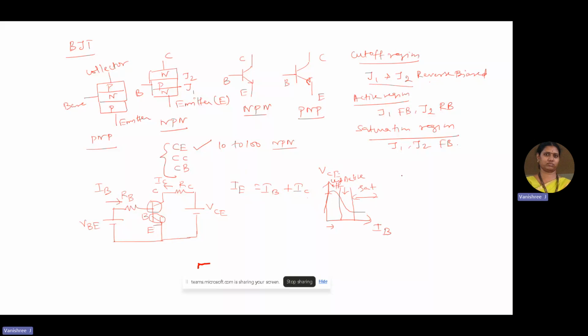So coming to the characteristic graphs, input-output characteristics. Input characteristics is drawn between VBE and IB for various constant values of VCE. So if you just look, initially it is required for us to spend some magnitude of VBE in order to reach the barrier potential and to make the rise in the base current. So it is this magnitude for the given value of VCE1.